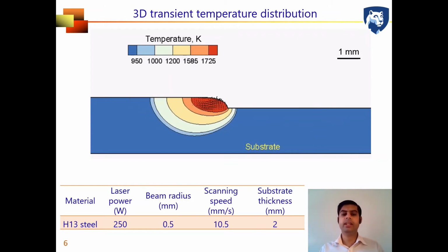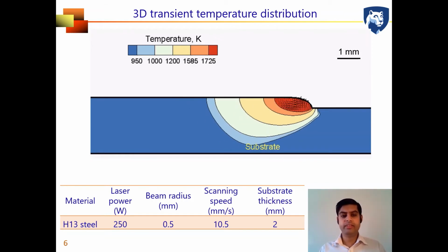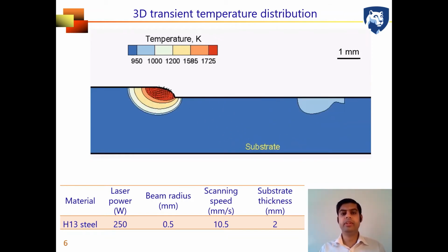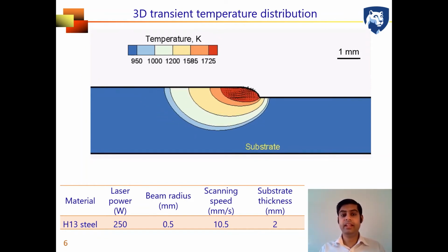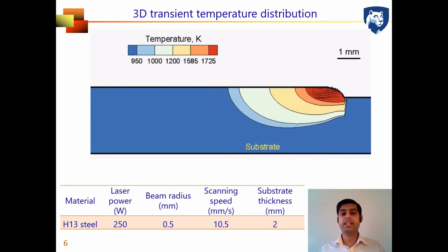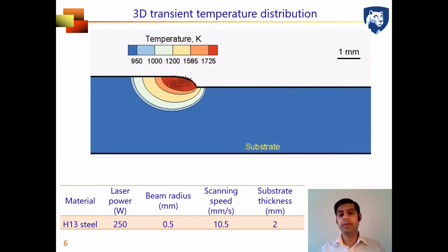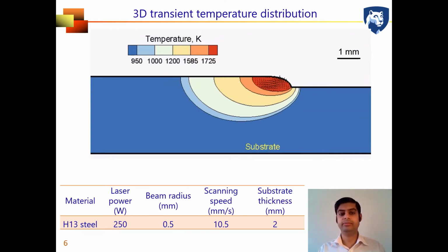So the bottom line from the animation is during the additive manufacturing process, while depositing many layers, the temperature fields vary in such a way that affect the microstructure and evolution of properties like hardness and their spatiotemporal variations.